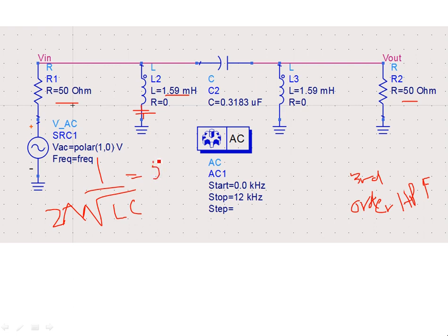So this is 500 kilohertz. Okay, 500k. So you have the inductor value, right? And if you just evaluate the expression, you will find out what the corresponding C is. Similarly, you have to do the same for the shunt LC branch.